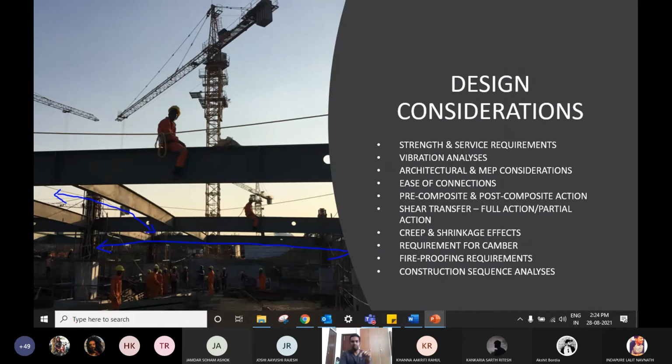So when you do that, you might end up making the structure more rigid, so your beam depths could now be larger in order to avoid that resonance. That's why I say your vibration analysis would determine your member sizes.